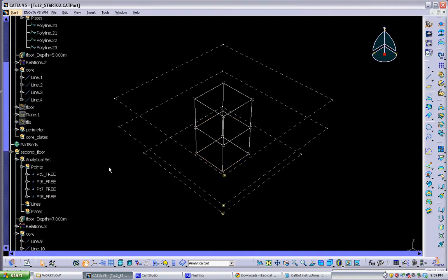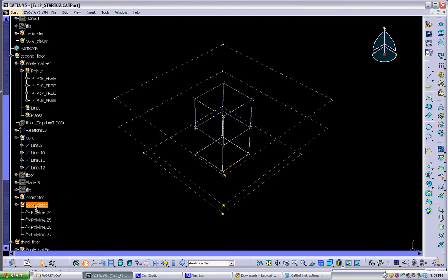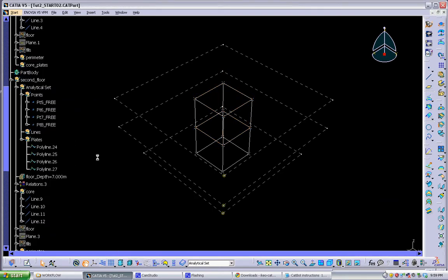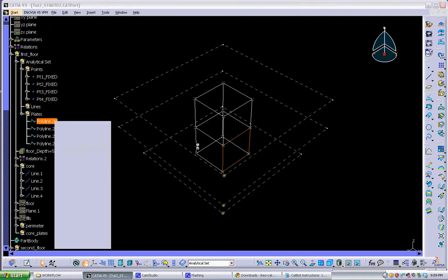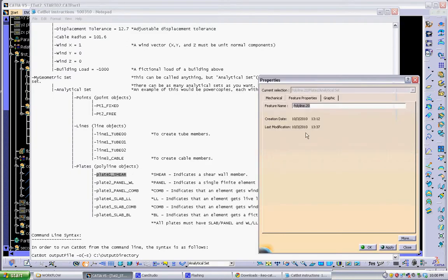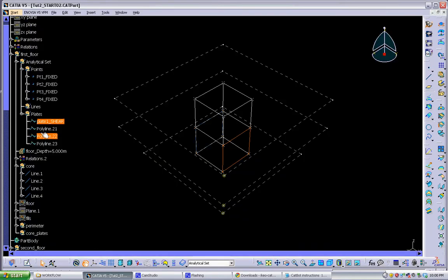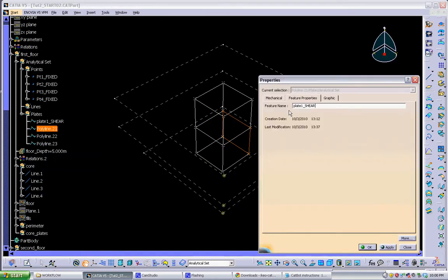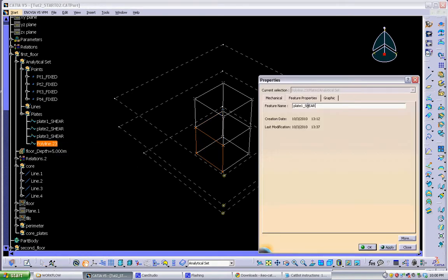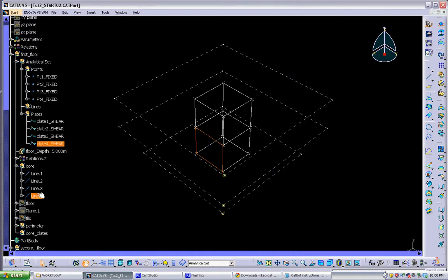And then I'm going to do the same thing for the second floor. And then I want to go through and rename them. So if you forgot what the naming convention is, again, you can go back to here. You can copy and paste this. Call plate 1, okay. And then go down and name them in order. Again, at this point, when you're not dealing with points, the sequential numbering doesn't matter too much, but you still want to name it something that makes sense, because then it'll be easier to check your results. So I'm just going to name these going down.